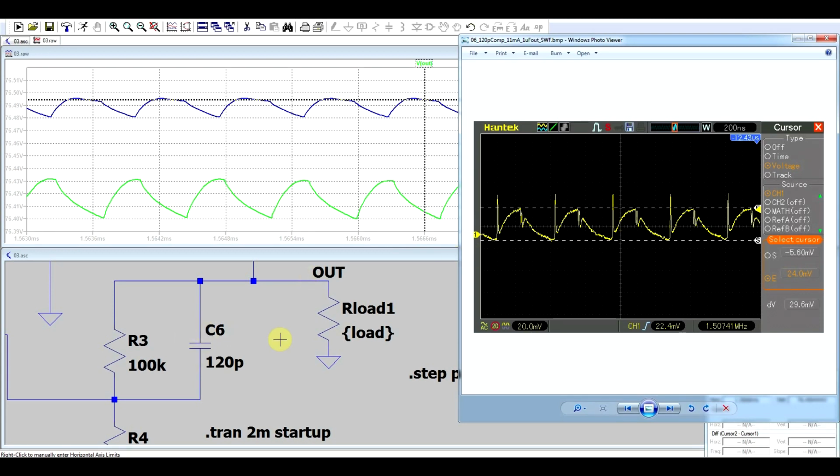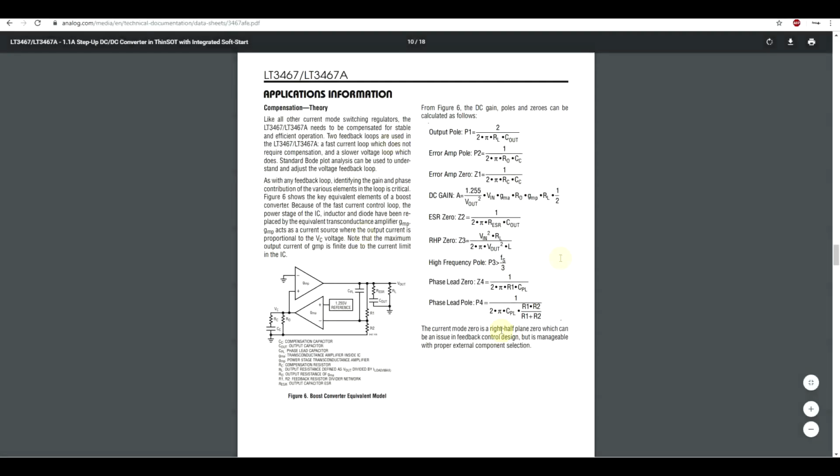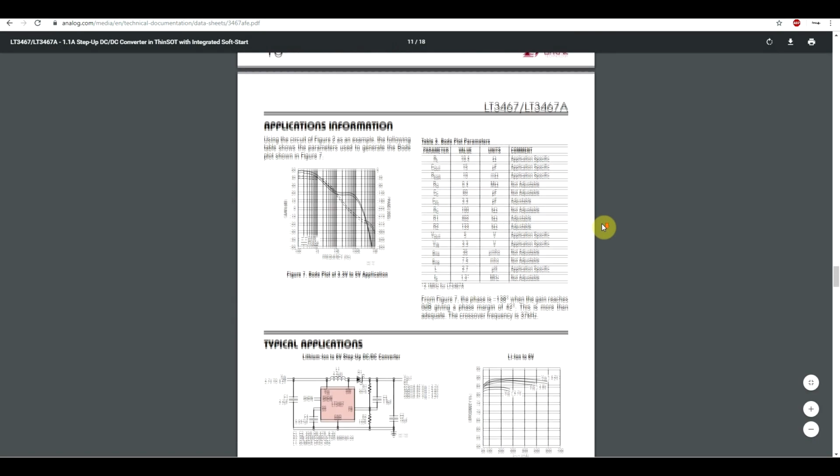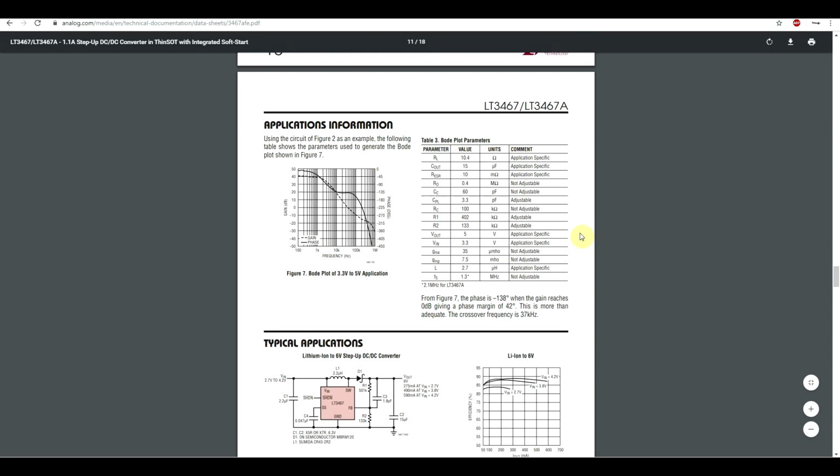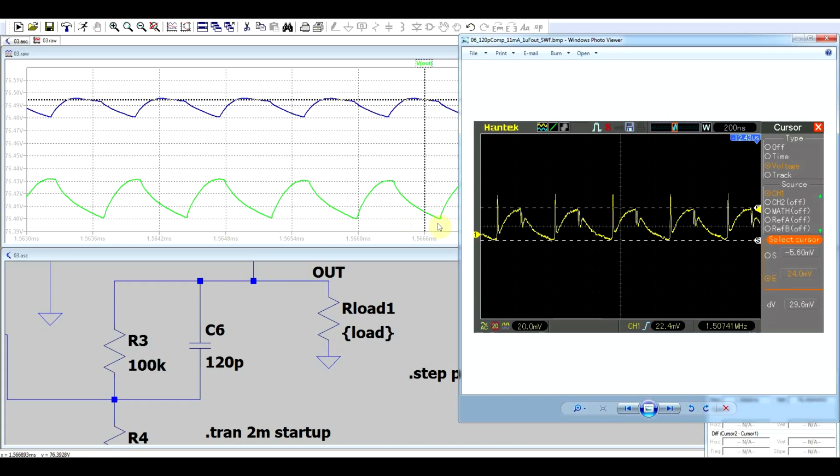Now it's important to mention here that adding extra output capacitors can have an influence on the system's stability. The output capacitance and its ESR are part of the stability calculations of a power supply. So especially after adding large capacitors to the output of a power supply, just make sure to check that the supply is still stable. Now it's time to analyze the high frequency noise.